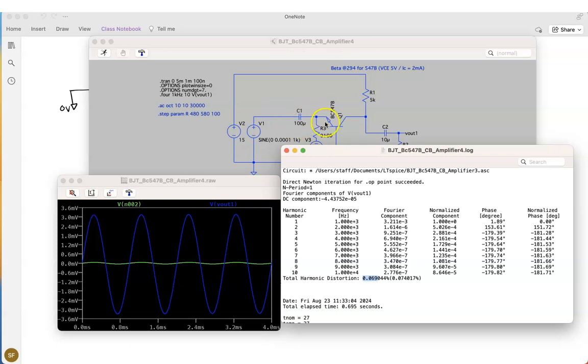Because if we think about small signal analysis, we've got this VBE, with an AC signal coming in which is superimposed on the DC operating point. This is going to cause variation, and as I mentioned earlier, the relationship between VBE and IC is exponential. So if we keep the variations small, then we can essentially approximate a linear relationship between the IC and VBE. However, as we make the variations larger, the relationship is exponential, so we see more distortion.